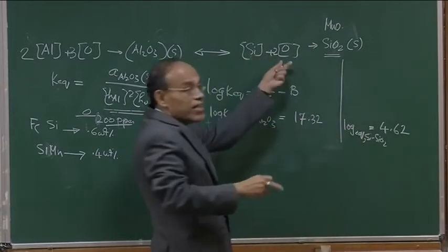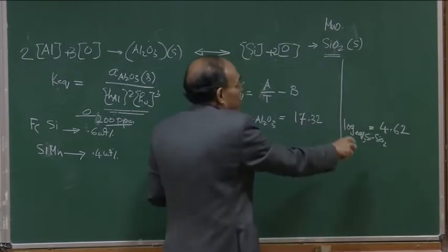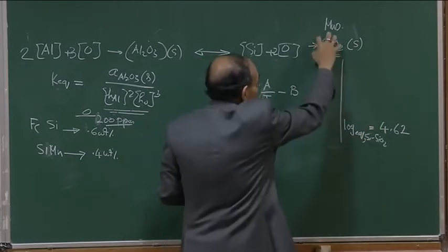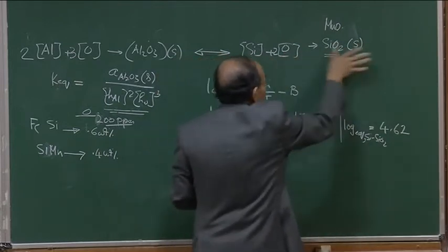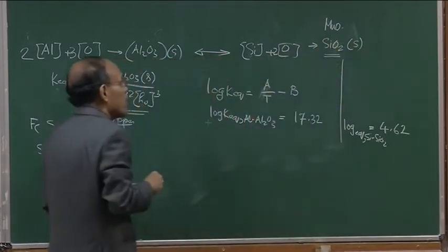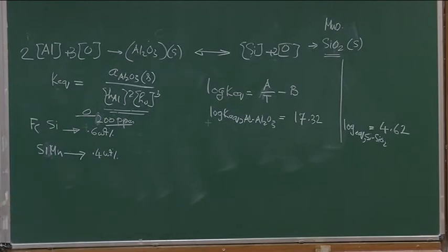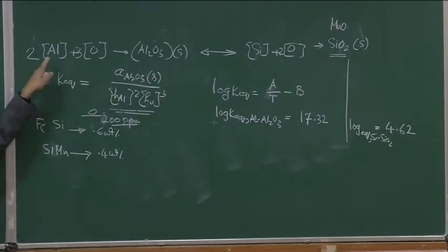the right. There is a tendency now to eliminate SiO2, and that is what is happening when you have manganese oxide there, which is reacting with and eating up silicon dioxide. So, the forward direction is the more preferential direction of the reaction. In that case, the efficiency of the deoxidation reaction really increases. So, the contamination, or the residual silicon content as a result of deoxidation, is lower. When the Al2O3 product has formed, some aluminum has gone into steel, and this aluminum is the residual aluminum due to deoxidation.